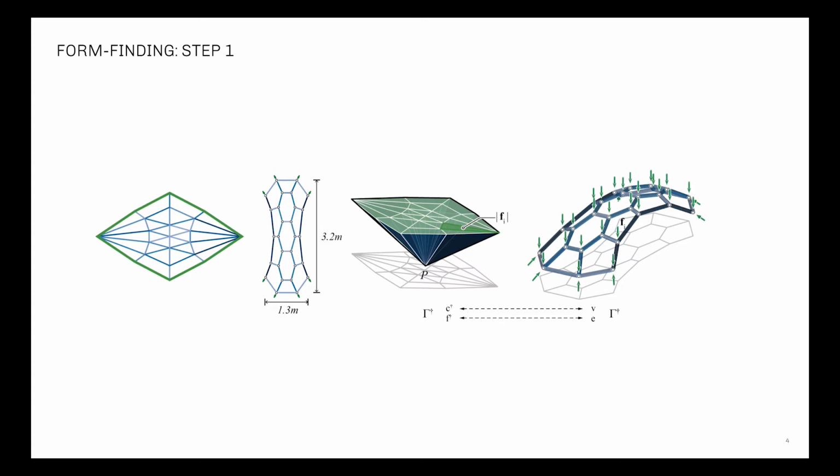The total area of the faces maps to the total applied load of 1 kN, and the area of each face maps to the magnitude of the tributary load on the corresponding node. By changing the areas of the polygonal faces, the distribution of the applied load can be manipulated.